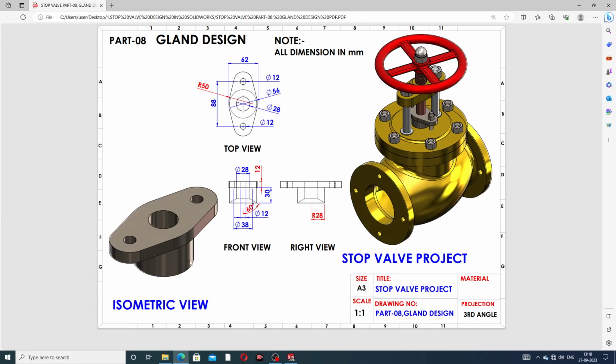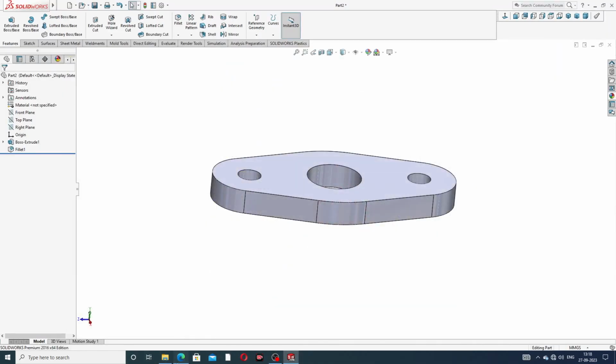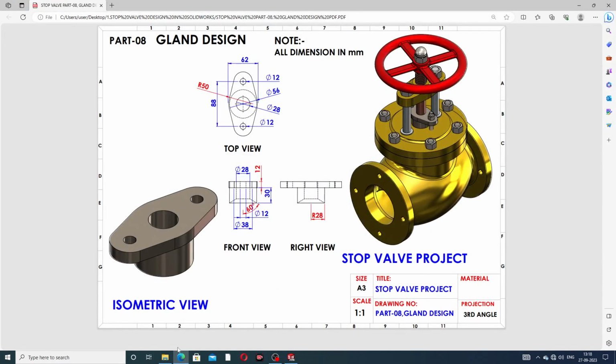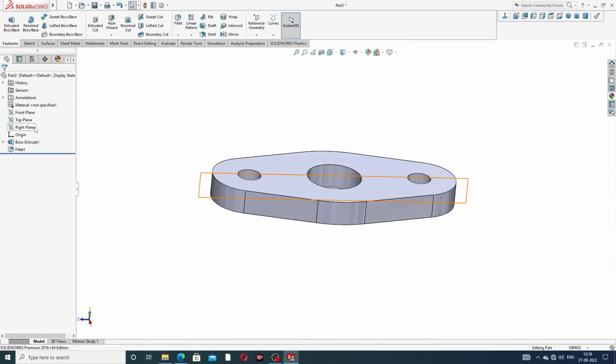And again select this line. This part is drawn here, and the upper part is drawn here easily, and this distance is 28 millimeter, and this angle is 60-degree angle. Okay, and all is perfect. Okay, and this length is 30 millimeter. Okay, and again select.